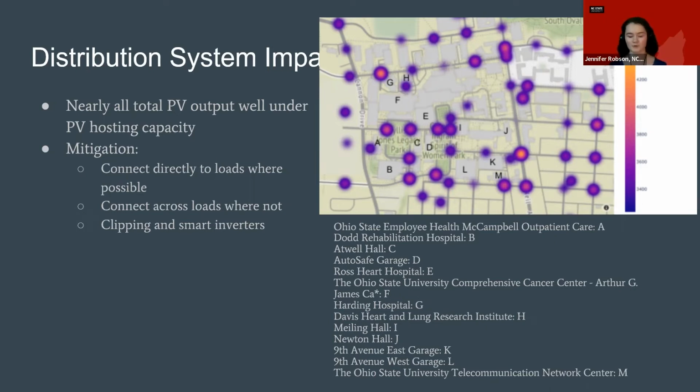Assuming that OSU takes in 3-phase power, we can connect the parking garages and the field to different phases of that power to make sure there's always a load in between and thus always a voltage drop. Furthermore, smart inverters and sensors will be placed to clip the output if any overvoltage conditions are met in accordance to the utility standard at that area.